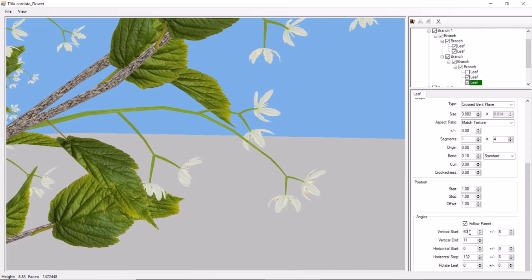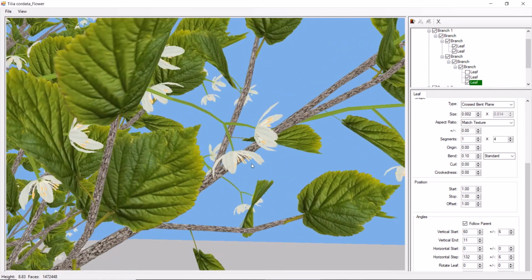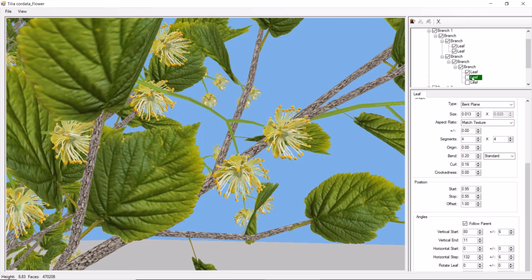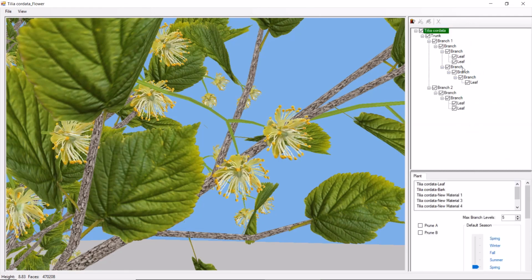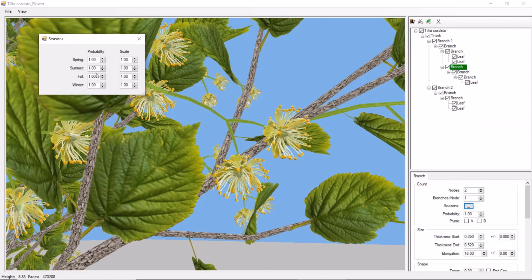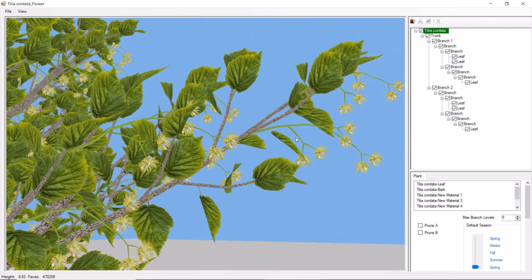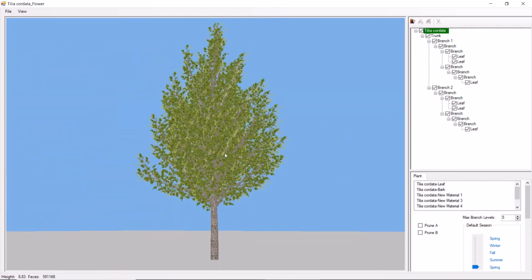This would be another way to create these elements, although in this case, it is not advisable to reach this level of detail for a tree, because, as you can see in the lower left part, being such a detailed element and repeated so many times, it considerably increases the number of segments or faces of this mesh that we will later export. And if we are going to work with a large number of specimens, it will make working with this modeling much slower and more complicated. Therefore, it is more convenient to use the first option and finish setting up the seasons.